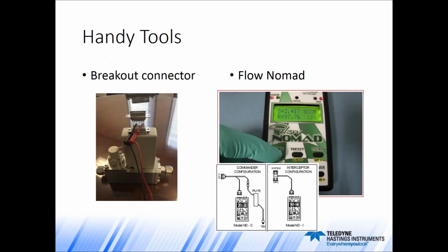Now, if you find yourself needing to drill down into the wiring issue, we have some tools that can help. One of the simplest, shown on the left, is a breakout connector that will allow you to measure in and reach and measure voltage levels. And we're happy to loan these out to users to help them troubleshoot. We're also willing to loan out our single channel power supplies if you ever need that, the THCD 100. Now on the right, I've shown a picture of the Flow Nomad, which is available from SemiFlow. This device allows the user to analyze analog signals between the MFC and the power supply.